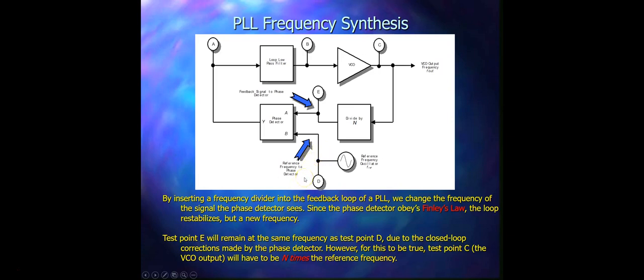So here we found that by modifying the feedback portion of the loop, we can get the loop to produce new frequencies. We saw that here. A frequency divider is a circuit dividing an incoming frequency by some chosen number, and this number can be any, depending upon your circuit conditions. These frequency dividers are really nothing more than digital counters. If you get into detail, you will get to know that. The addition of the divider within the feedback portion of the loop changes the signal that the phase detector basically sees at this point.